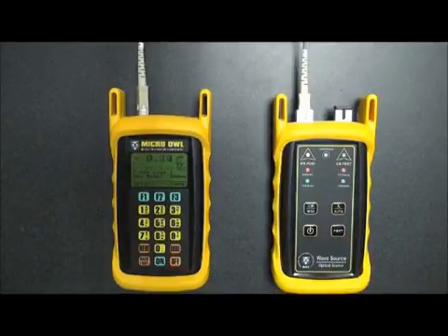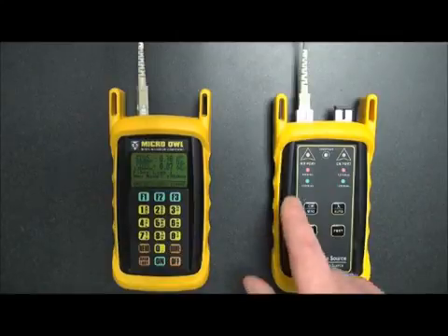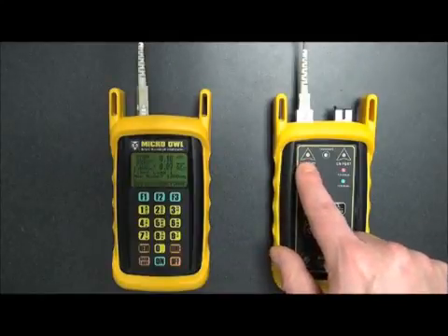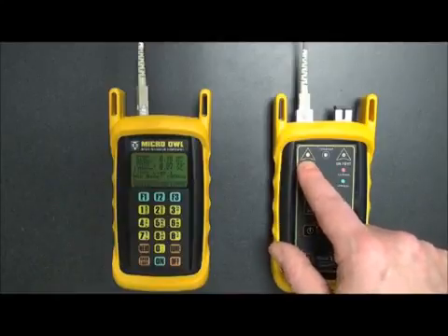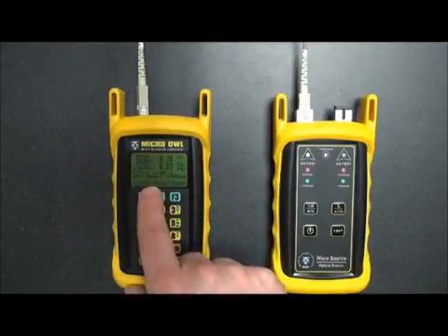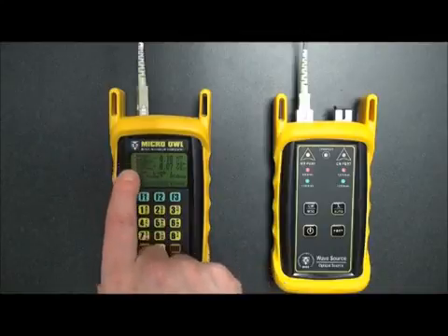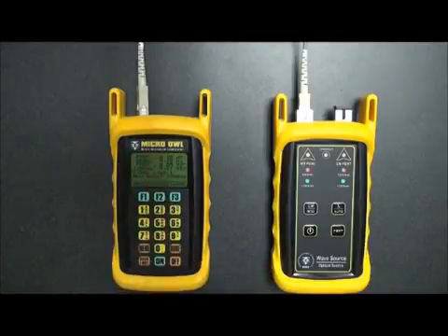Okay, as you can see, it took me a couple tries here. But now, once you know you'll be in auto mode when you see that this indicator LED is alternating between different colors and between flashing and solid. And over here on the micro owl screen, you'll see that both wavelengths show up. You see that you're very close to 0 on both sides, or both wavelengths. So what this means is that you set a reference for both wavelengths. You've set the meter and source into auto mode.